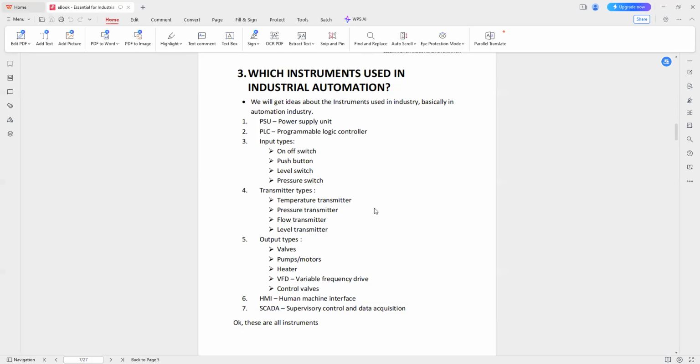In small scale or medium scale machines, you can use HMI, but in a process industry, or in a big project, you need to use a SCADA system, because the features are more and it is more reliable. So HMI and SCADA are for visualization, operating and monitoring. The user has to control the system from HMI or SCADA and monitor how the system and the operation are working.